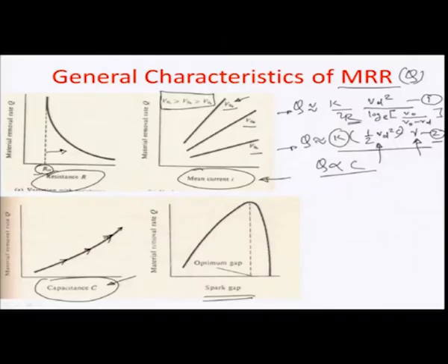As is obvious, Vd, or discharge voltage, is equal to 72% of the operating voltage for maximum power transfer, which we had calculated and shown in detail earlier. And so, if the operating voltage is more, the discharge voltage also subsequently rises.